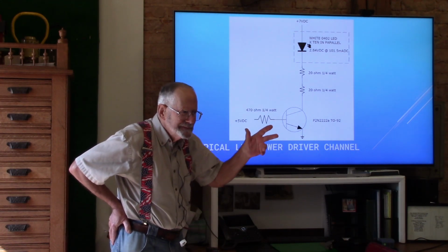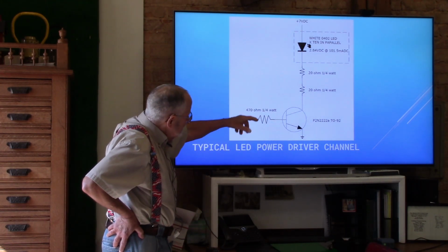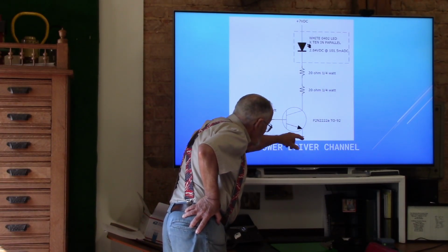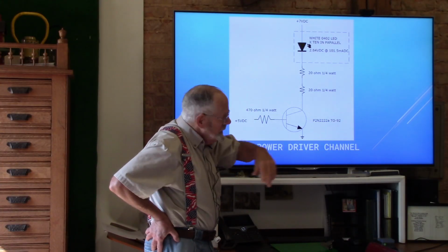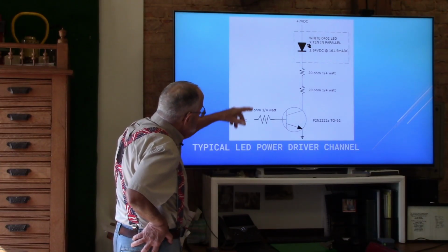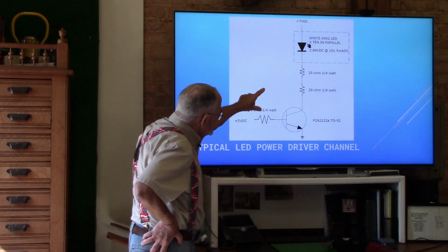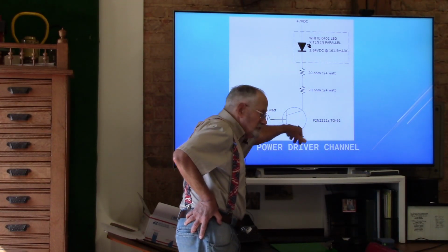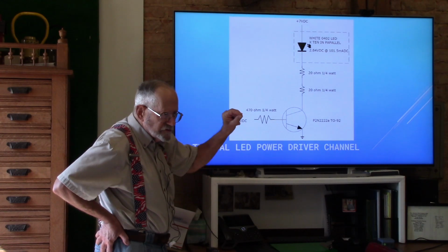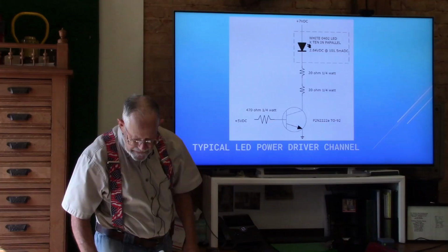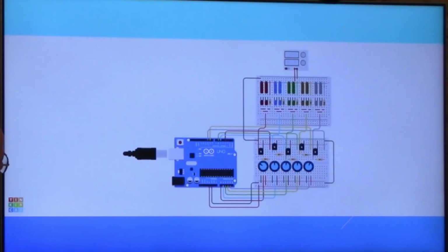It's around 100. And what I need is, and don't forget, there's a drop across here, which is about 0.2 of a volt. So we're taking 7 volts, and we have to subtract 2.84, and then subtract this 0.2, which is the drop across the switching transistor when it's turned on. And you have to do that for each channel. So that's a lot of power.